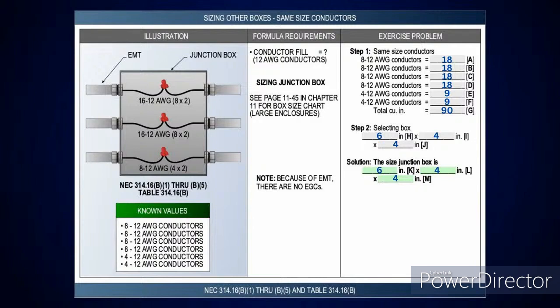You can even shove that back in the knockout. Remember that one? Oh yeah, I do. And that cubic inch was 96 cubic inches, so it was just right above 90 cubic inches for that size box. Nice.